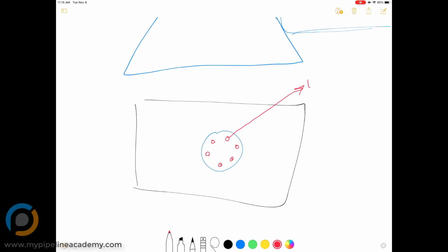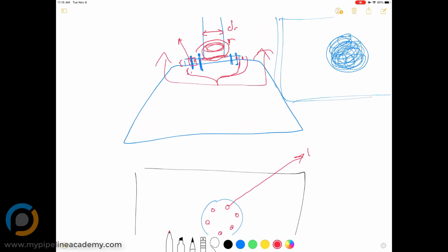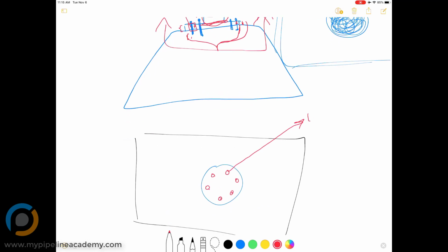Yep. That's exactly right. Now, let's take this one step further. What material are screws usually made out of? Steel. Steel, right. So if that's the case, are we going to use the same yield strength that we used before? No, but that should be on the McMaster website too, right? They should tell us the yield strength for that particular material that the screw is made of. Yep. And if not, you estimate it. McMaster will tell you what the material is, and you can go off and search for the yield strength for that particular material.